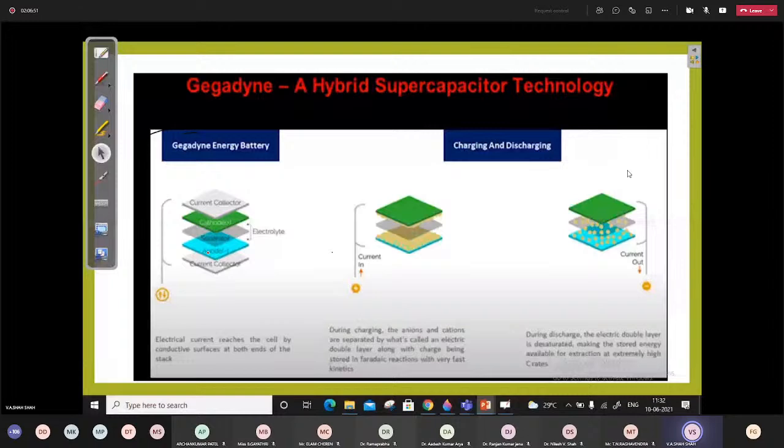So if I am using UC, then UC has to supply this and the battery has to supply this. But let's say I'm designing only a battery operated vehicle. Then in that case the battery has to supply this much peak power also, along with this average power. So the battery current: let's say I'm selecting a battery with a voltage of 48 volt without UC, assuming maximum discharge current per cell is 5 ampere with a peak voltage of 4.2 volt. Then how many battery cells do we need to connect in series? That is 48 divided by 4.2.